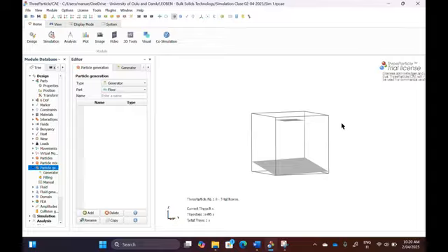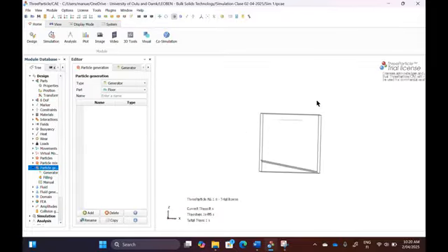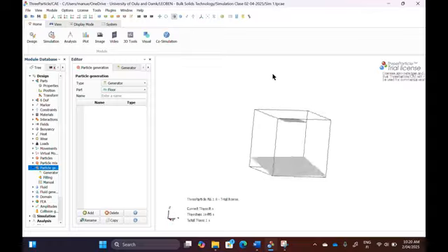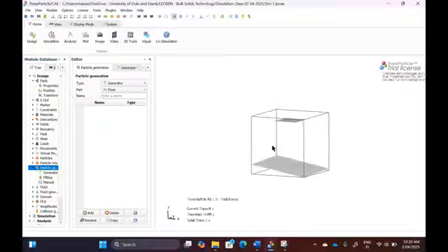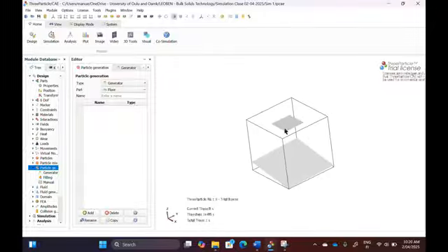No, planes, because that's what we're defining here. I want to include the generator, which has to be a plane. Not a box, not a cylinder, but a plane. Give it a name, for example, generator plane. And then it appears. And if I double click it, I get a bar here, where I can set the major properties of the particles, change the color, for example, to, I don't know, pink, basic things. And the second things are one part after that. You can change the size here, the dimension, the orientation, and where it is in space. It should look something like that.